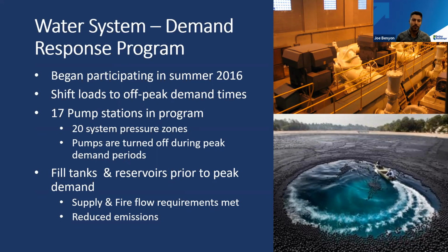And just as a quick fun fact, our water control group and our operations has been doing a form of demand response for years, even before we began participating in 2016. Our controls group looks at the system and, any hot day, we typically try to crowd our tanks before the peak heat, just to make sure that we have enough water in our tanks for emergencies and for fires. Next slide, please.